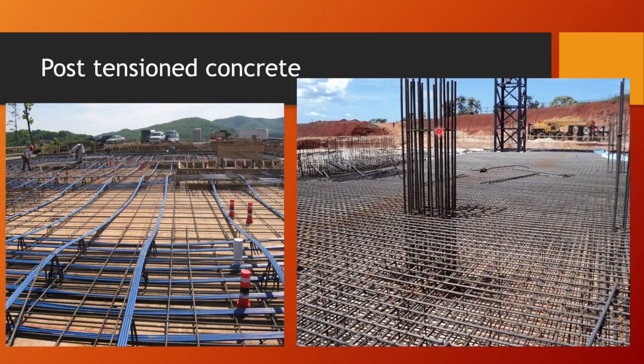I think minimum 500mm or 50cm would be sticking out, because that's the requirement for what we call splicing. So to continue the column up for the next lift, the next floor, the reinforcement bar would be tied to these, at least half a metre, 500mm splice, and then the next deck would be poured, and that's how we do continuous column forming.